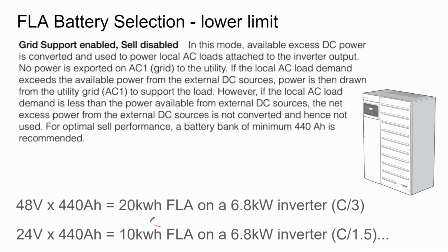Now, you could not use this 10 kilowatt hour battery all at once. What it's really there for is to turn the battery inverter on during the day and allow the solar array to be on with the battery inverter, so that you can use your energy during the day and then hunker down at night.